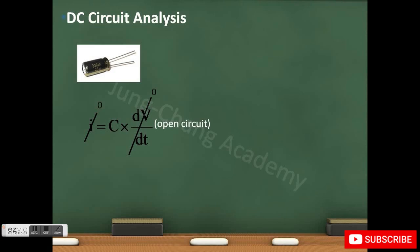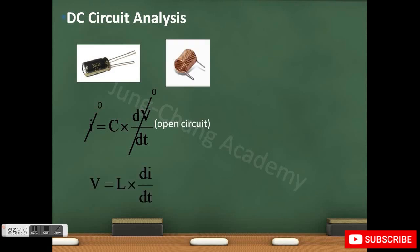Similarly, the voltage across the inductor is equal to the inductance times the change in current. Again, since the DC source supplies a constant current, the voltage across the inductor in this case will be 0, meaning the inductor will look like a short circuit.